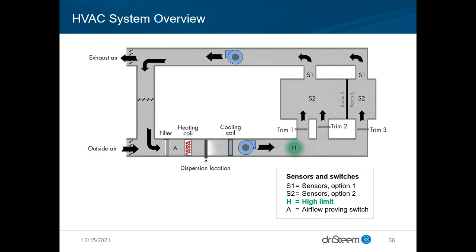So these high limits are put typically about 8 feet down from the humidifier and set to shut off the humidifier at about 90%. And there's options where you can have a modulating high limit, where you would set a lower level, say 80%, and then just between 80 and 90, throttle back your demand, but still humidify to not fully shut off if possible.